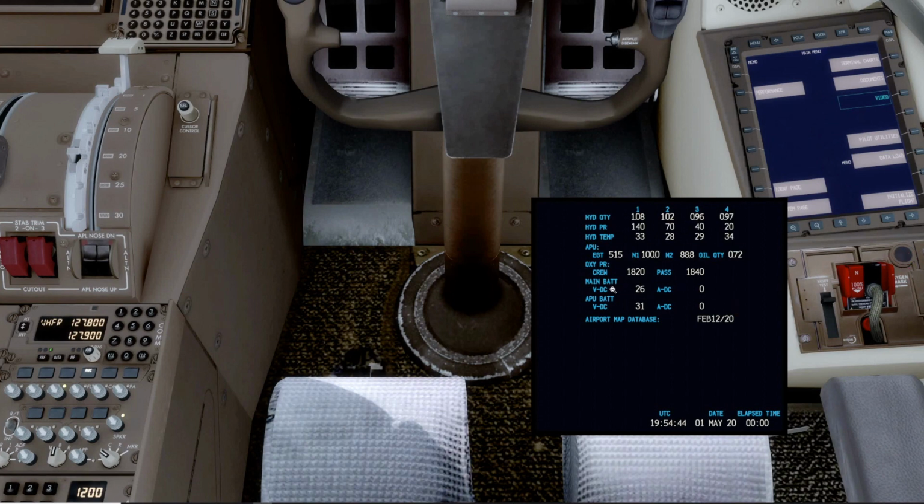And then you're going to check the status page to see that the oxygen pressure doesn't drop more than 100 psi. So you'd hold the reset test lever down, at the same time go to the emergency switch and push that. So I'll do that kind of quickly here. Push it down, go over here, push, and now you'll see it's continuous. And I can hear it vaguely. I don't have the sound turned way up, but I can hear it. And I hold that for 10 seconds. And then I check the oxygen crew pressure doesn't drop by more than 100 psi.